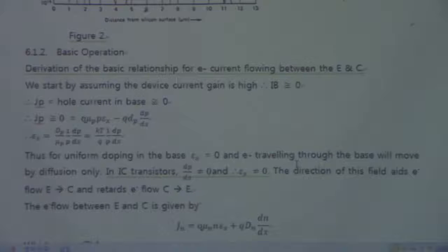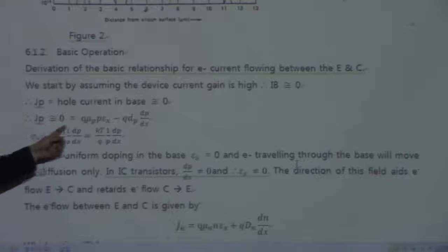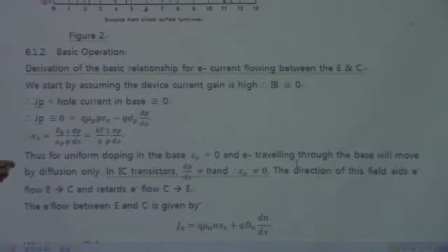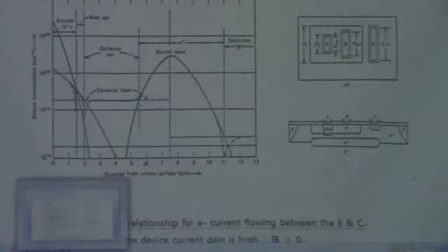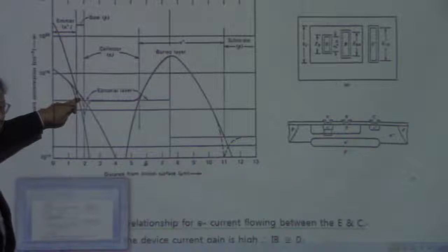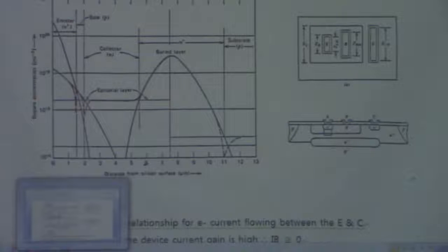established between the emitter and base with this assumption, and that turned out to be something like this. We just assume that in the base we have a uniform concentration, but in reality the boron concentration cannot be uniform in the base, because we are going to do that by implantation, and we expect a Gaussian profile in the base.